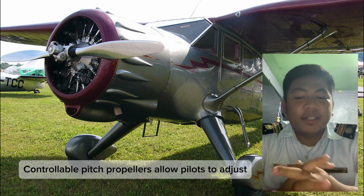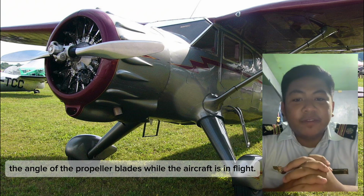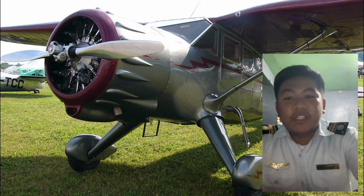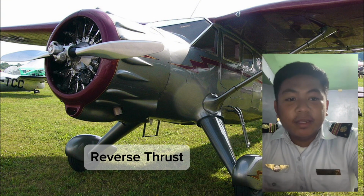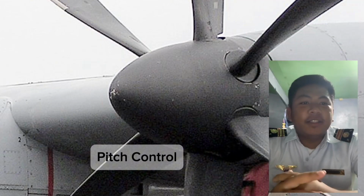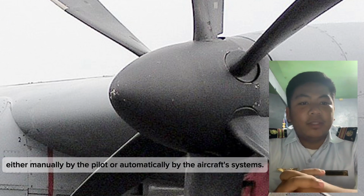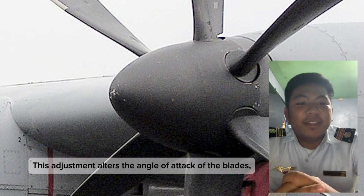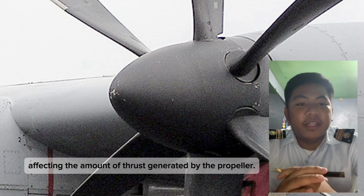Controllable pitch propellers allow the pilot to adjust the angle of the propeller blades while the aircraft is in flight. The principles of their operation involve pitch control, variable thrust, feathering, reverse thrust, and automation integration. Pitch control. The pitch angle of the blades can be adjusted either manually by the pilot or automatically by the aircraft systems. This adjustment alters the angle of attack of the blades, affecting the amount of thrust generated by the propeller.